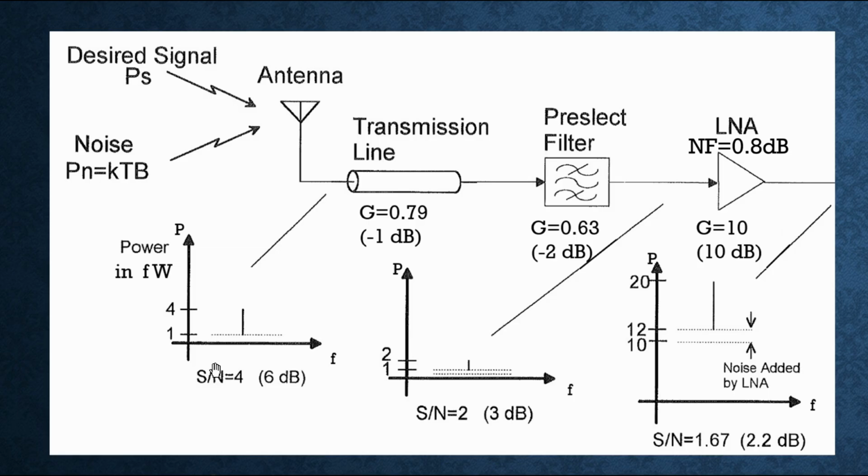And what about the noise power? Well, the 1 femtowatt got cut in half, but there are resistive losses involved here, and that's where the loss of the filter and the transmission line come from. And so the way this works out, it's hard to show, but really easy to work with. If you stand on the right side of this filter and you look back through, you just see a bunch of passive losses and then the signal coming in.